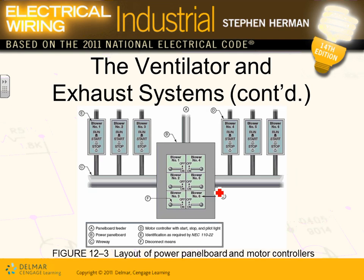Okay, for the project that we have, guys, remember we have 2 projects. We have this project that we're dealing with, and the project that you guys are working on. This is how all these exhaust fans are located on the roof for this industrial building, and they're powered from right in here. And we have a controller. Each one of them has a controller, a magnetic starter, a push button, and a couple of lights to give you green running, red not running. So you can push any of these buttons and turn any of these exhaust fans on and off. And they're all powered with a fuse disconnect coming out of this.